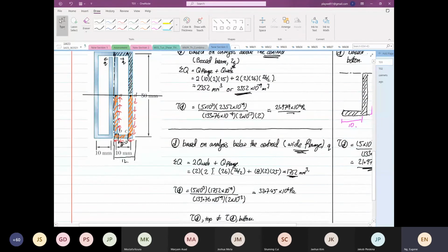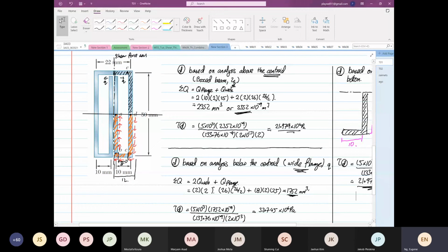The question now is this. What I'm looking for is what rule is it? Why we don't consider the entire structure in orange? Is it because rule 3 says analysis starts at y max, so we start at y max, which is the very bottom, and then we go to D, but the other web has nothing to do with D, so we don't include it. Because D is not on the other web, so we only include the flange and the web that D is on. Yeah, but what is the indication? The shear flow is going the opposite direction.